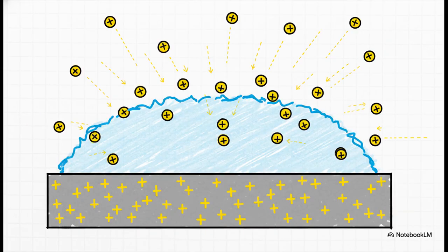So what happens when you build up a layer of positive charge? Well, it creates this invisible shield. Any new incoming positive argon ions are simply repelled by it before they can even reach the target. And within microseconds, the entire sputtering process just stops, dead in its tracks.